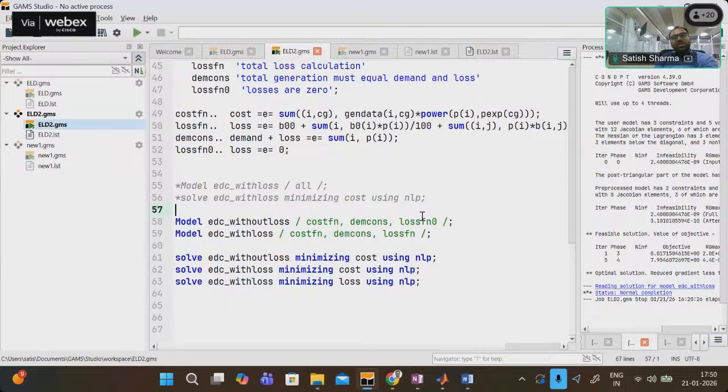Somebody mentioned in one question as well how the ramp limits will affect this. Yes, we cannot increase the production from 0 to, let's say, 100 megawatts instantly. It takes time, because it's a mechanical generator and production has to be increased over time. Those are called ramp limits. So let's say in a particular hour you ask that generator number 3 should produce a very small amount of power, and then another generator has to be turned off and again turned on. You cannot do that.